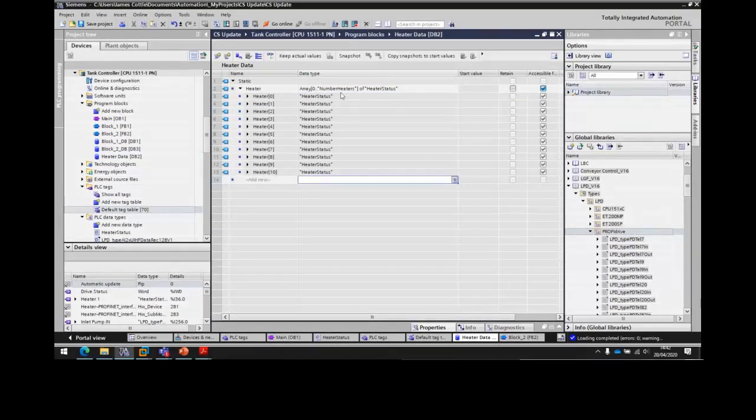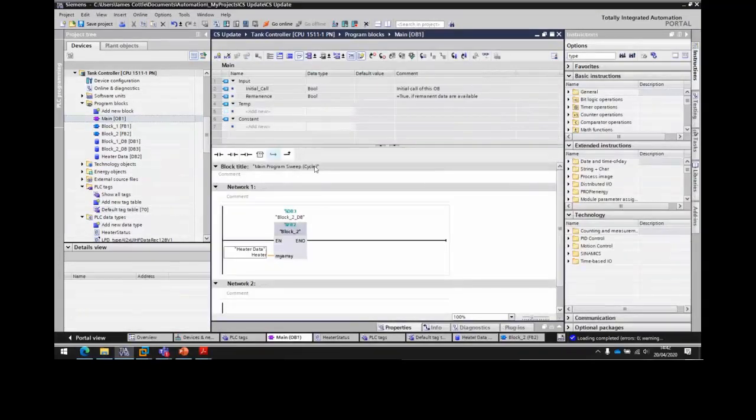However, through using the constants like this with arrays, we can run into some challenges which you should remember when programming. So right now, if you remember, I've got my function block and I've got it connected to that bit in the data block I'm currently scaling up and down. If you remember, when we created this function block, I defined the array on the in-out, and I defined it as an array of 0 to 10.